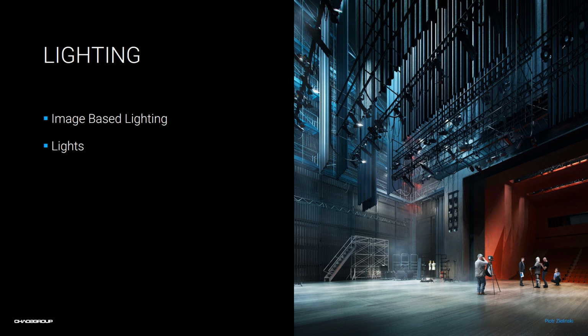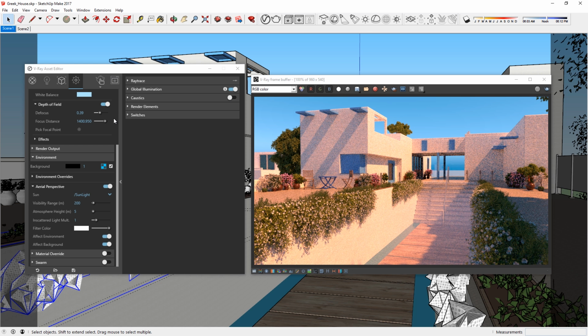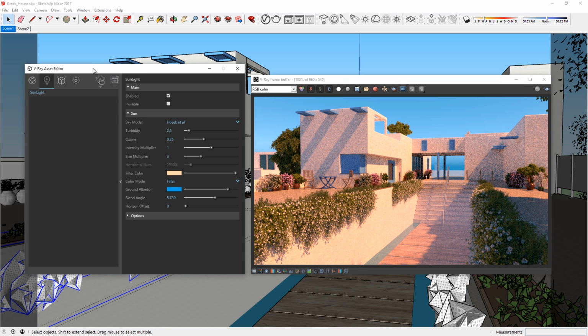Not only this is very easy, but it gives us great shadows, great reflections, and very versatile illumination. And then we'll combine all of this with artificial custom lights that you can do for all kinds of setup in your scene. Okay, going into SketchUp itself. Let's illuminate the scene using a dome light, but first I'll turn off the sun.